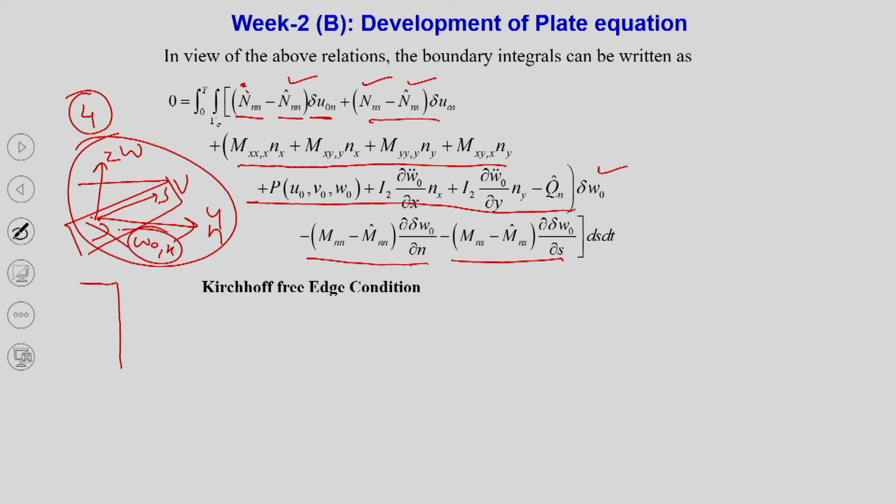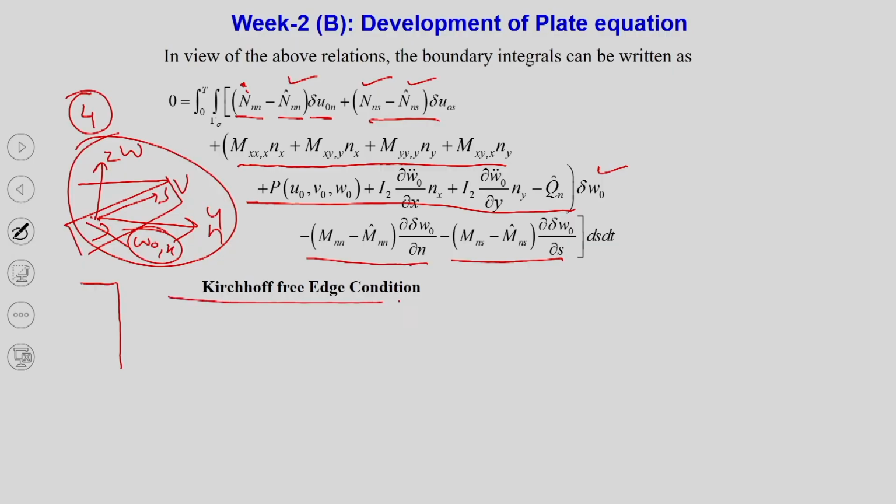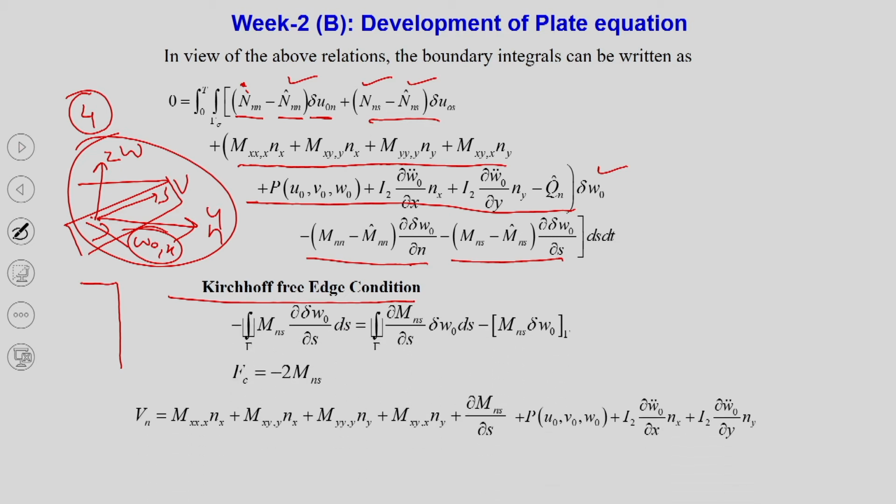So, if you talk about a clamped boundary condition, this is your condition. So, the Kirchhoff theory needs to rectify this system. Further, for del w naught comma s, again you do the partial integration, the first function as it is, differentiation of that and so on. So, basically this term remains on the boundary and this term goes to the corner.